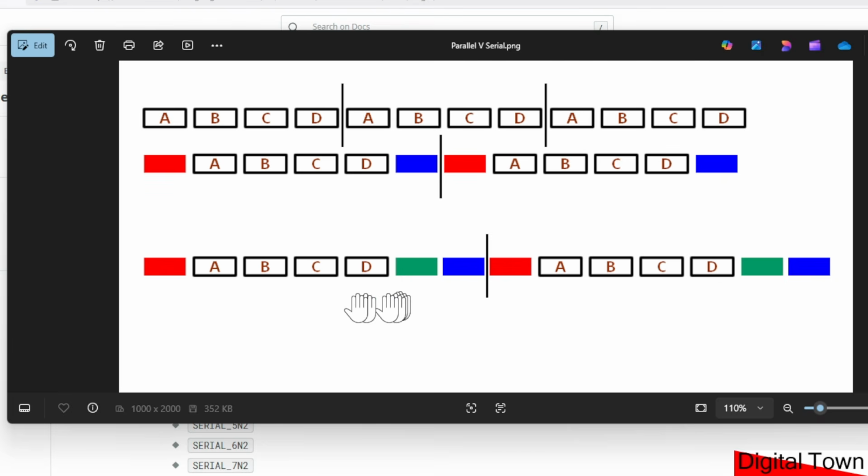For this simple example, all we're going to do is add these values together and take the low byte value, because that's the value that will change the most. The reason for doing this is that when the data is received, we can do the same calculation. So mathematically, this value at the receive end should be the same as at the transmission end.